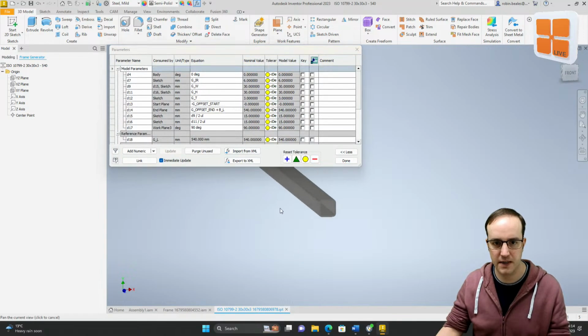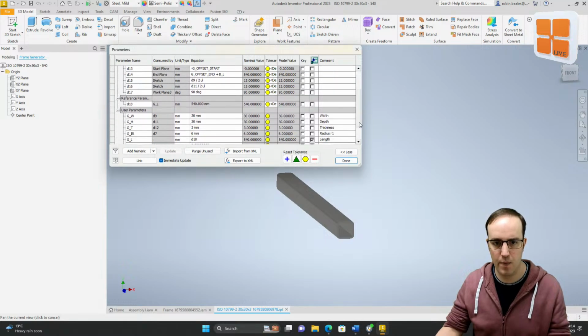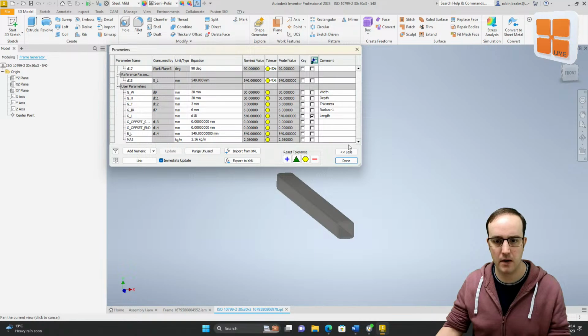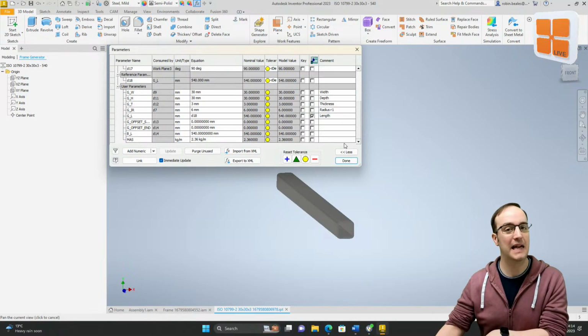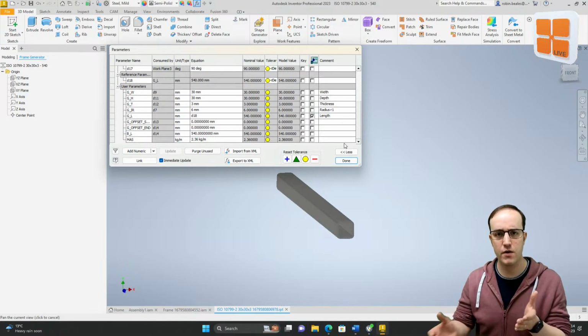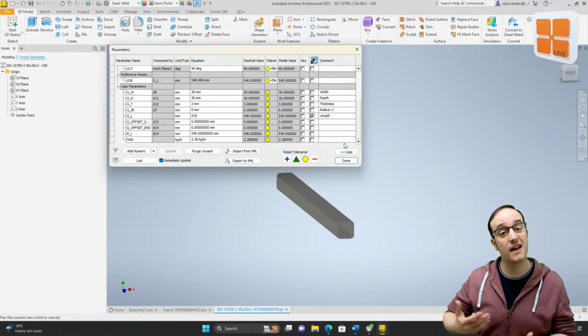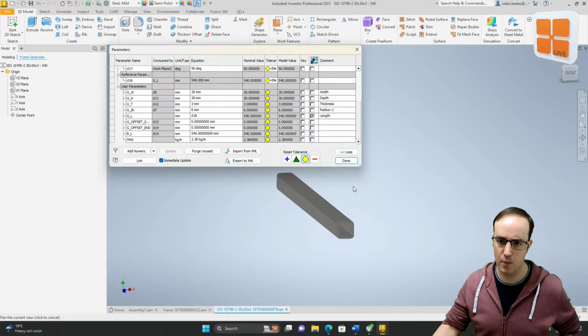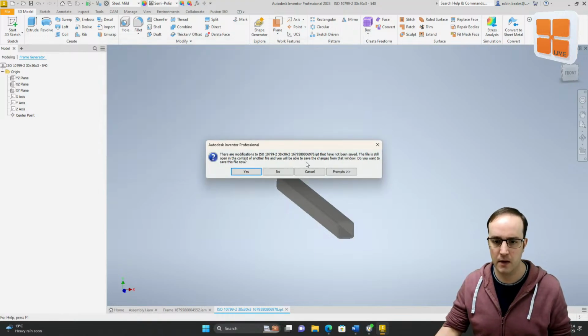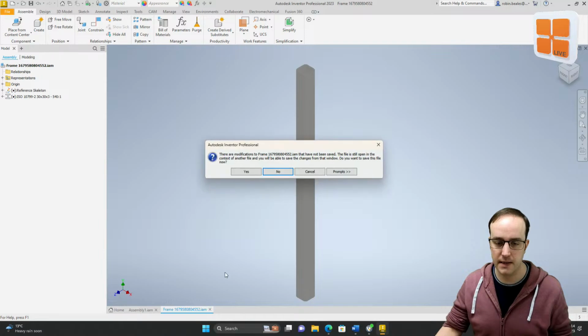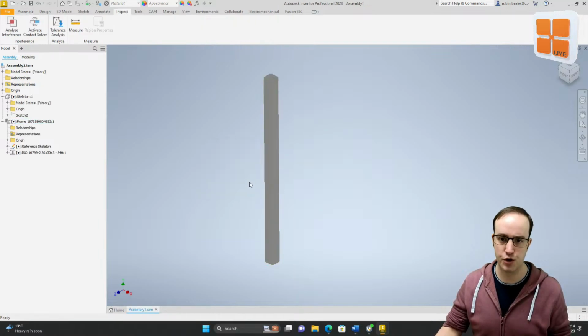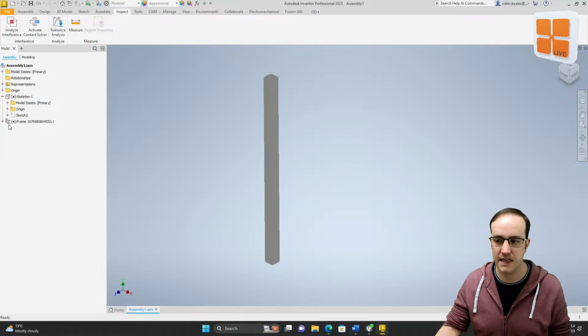So all of these components have properties such as GL, and GL will be your generated length for that part. Tube and pipe works very similarly inside of Inventor, where you get a pipe length, and these GLs, generated length, can be used to get cut lengths and cut lists within your BOMs in your assembly should you want them. So all I've done is, let's be honest, a glorified extrusion, but using a standard section. Yes, the sections can be customized, and yes, you can use your own custom content center to create them.